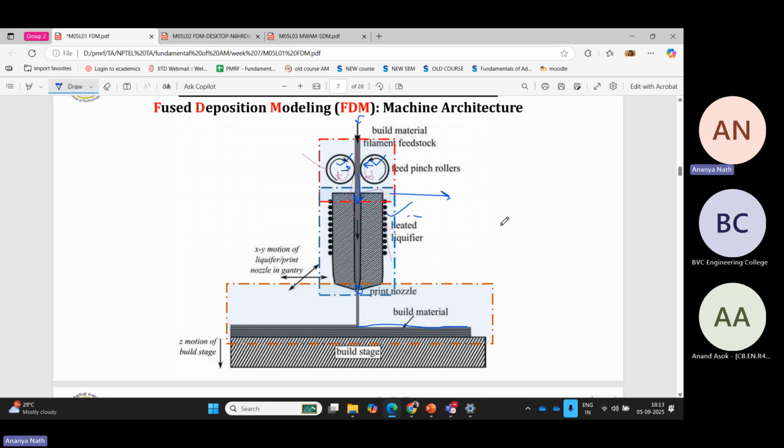Generally, in case of wire additive manufacturing, where it's continuous feeding or any wire additive, your surface will be very much even. There will be no high peaks and valleys and undulations. The waviness will be there, but it's very little. In case of wire additive manufacturing, your surface will be good in comparison with the powder-based additive manufacturing process.